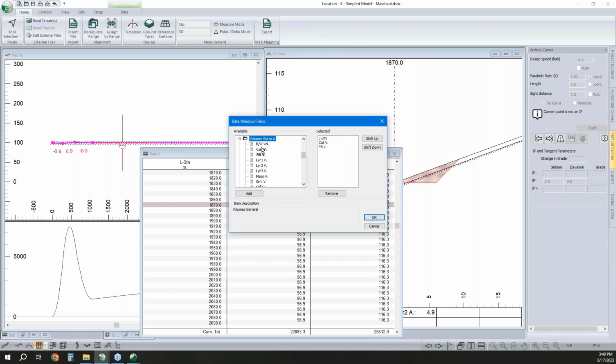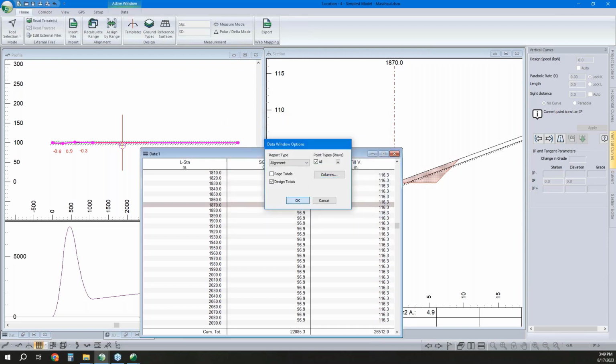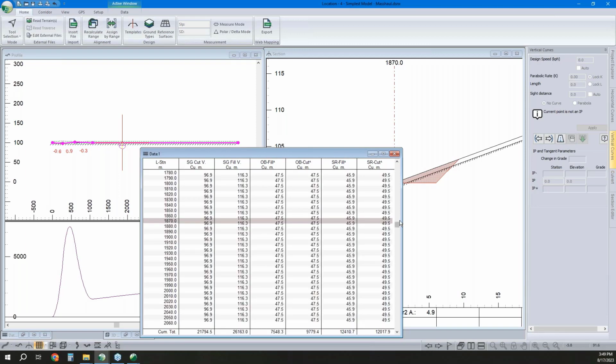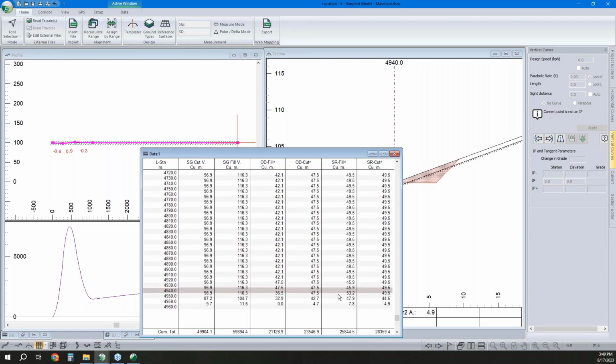That folder is referring to the conventional approach. We're going to break it down in more detail. So we're going to go cuts and fills by material here. We can see that, and if we add up these numbers, they're going to be inherently different. And we can see that for our fill through this section, let's go with 36.5 of our overburden, and we're using 53.2 of our solid rock.